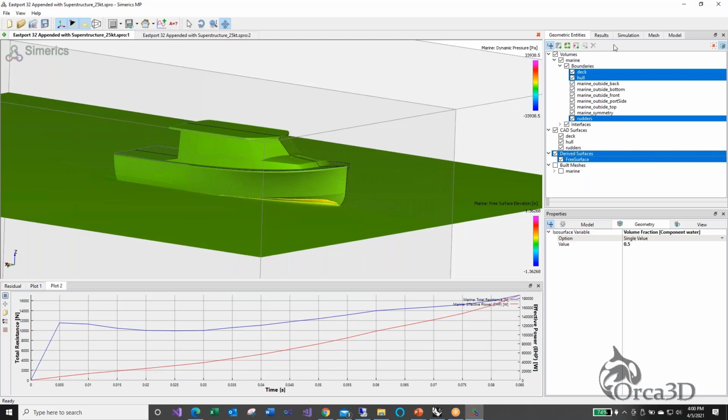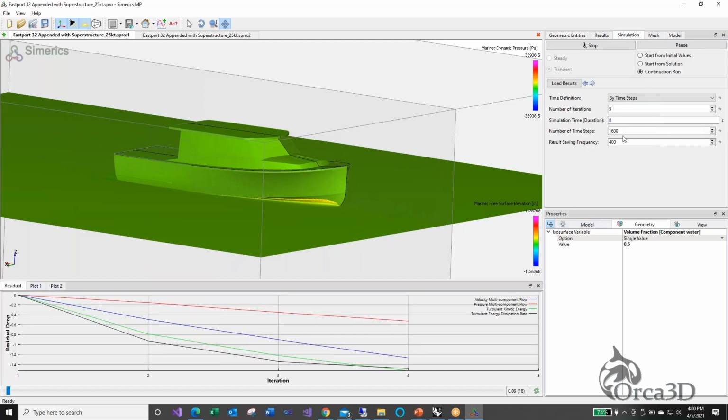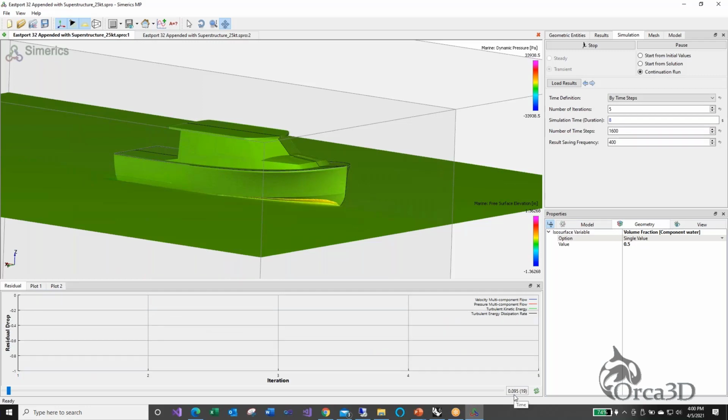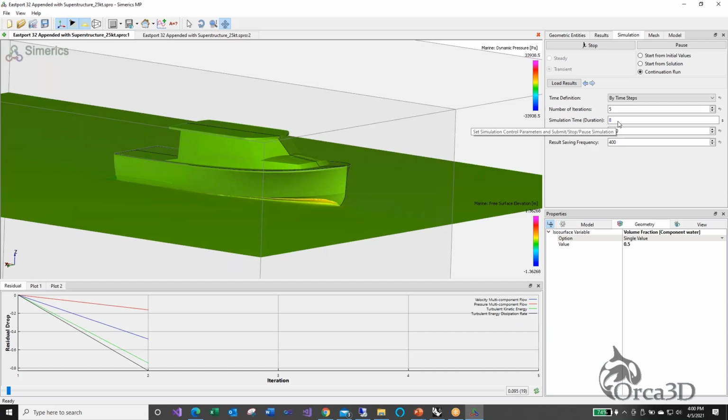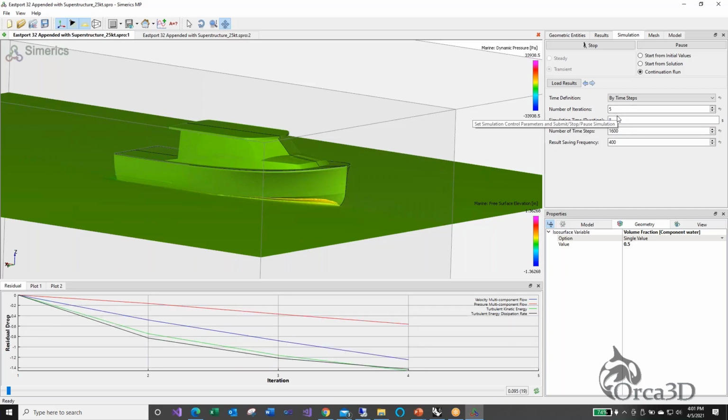So how do we know when the simulation is converged? Well, we know technically it's done at 8 seconds, right? Because the Marine template chose 8 seconds, and you can see we're now 0.09 seconds of the way through that simulation, just starting. So strictly speaking, from the point of view of this time duration, we know how long the simulation has to run. But what really defines how long the simulation should run is convergence of the results.